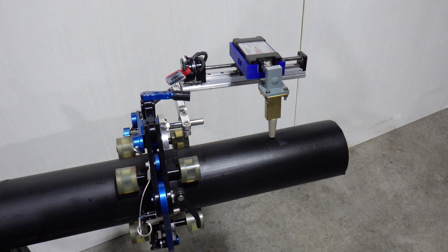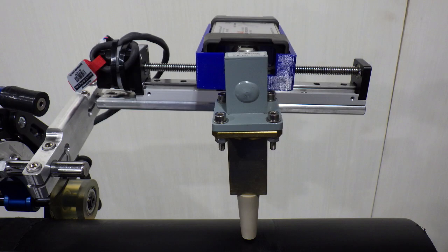This photo shows our microwave antenna attached to our chain scanner. This scanner allows us to rotate the antenna 360 degrees around the OD of the part being examined, while maintaining the proper air gap needed for the antenna. The scanner allows us to inspect parts with an OD from 4 inches to 30 inches.